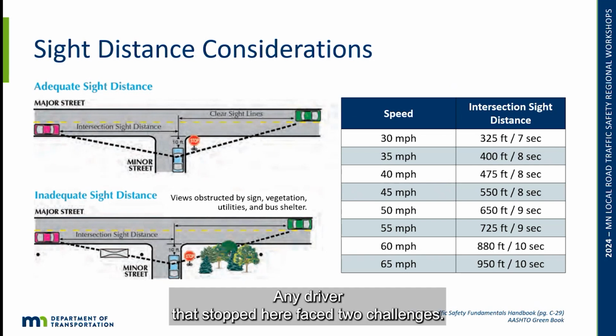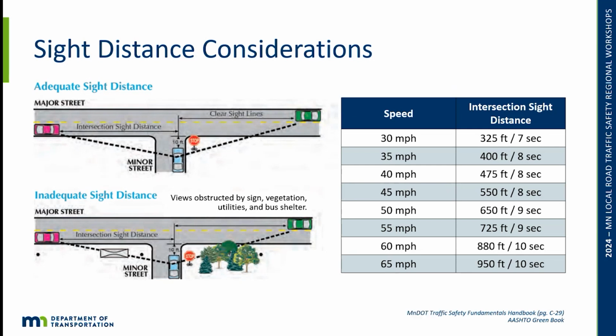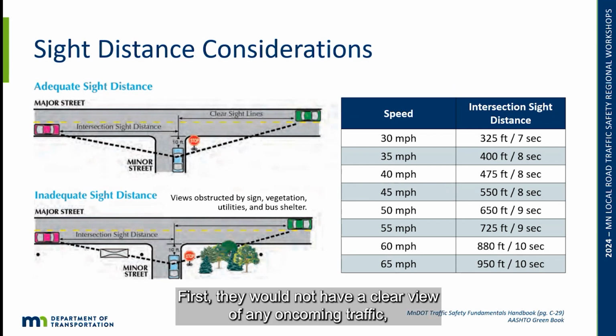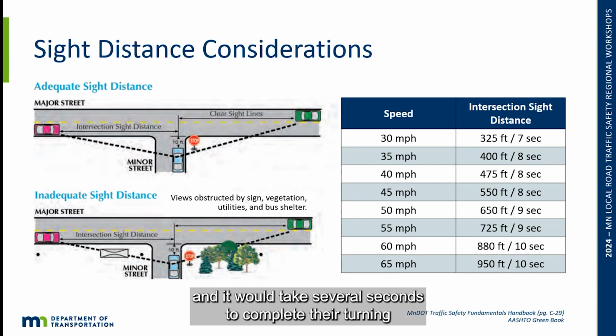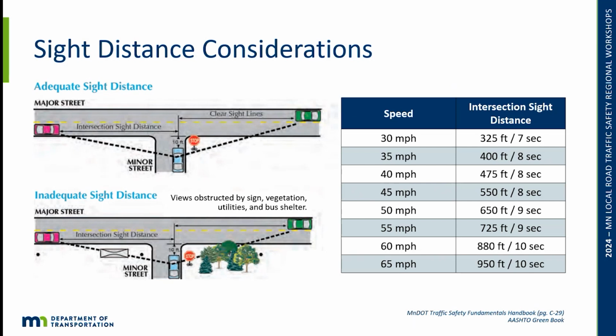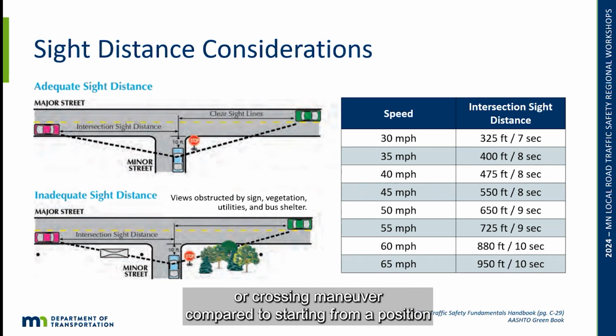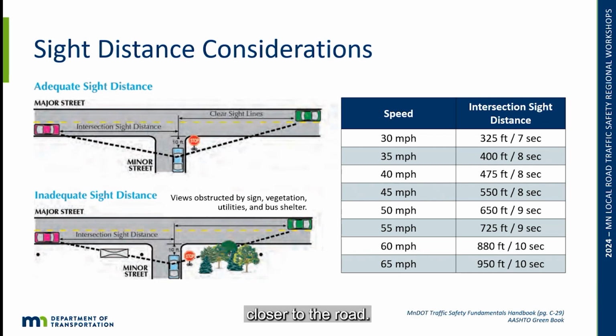Any driver that stopped here faced two challenges. First, they would not have a clear view of any oncoming traffic, and it would take several seconds to complete their turning or crossing maneuver compared to starting from a position closer to the through road.